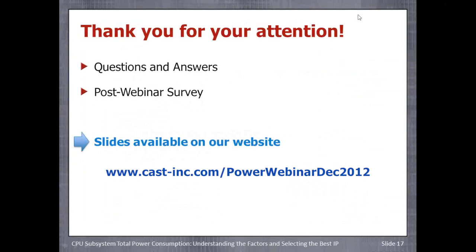Okay, I don't know whether that question applies to the B22 or is a general question. I would answer the general case though. Both are feasible with many processors. With the B22, you can use the software to put the CPU in a sleep mode, and then it would be woken from an interrupt that would come through a timer that keeps running or some external source.